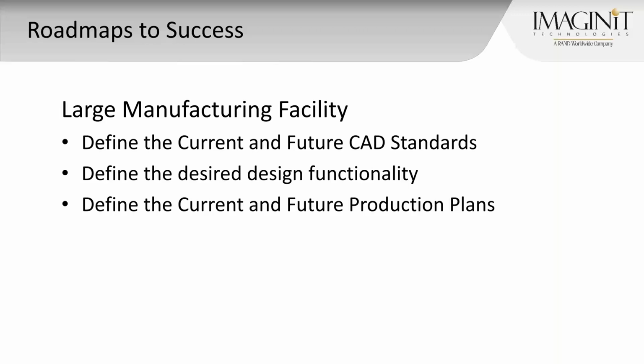One of the biggest things we have in going from MicroStation to AutoCAD is you have to remember that it's controlled by a translation table, and that translation is 1-to-1. So whatever is in that MicroStation drawing, it's going to be translated into that AutoCAD drawing, and it may be split up. That translation may cause it to create 2 AutoCAD drawings or 3 AutoCAD drawings, depending on the nesting within that DGN. So you have to be aware of that happening. And so when the DGNs are translated, the nesting is critical.